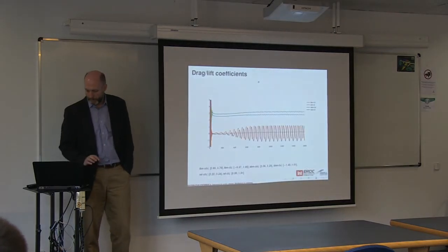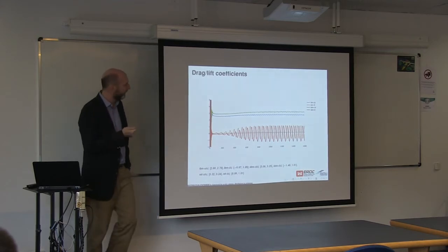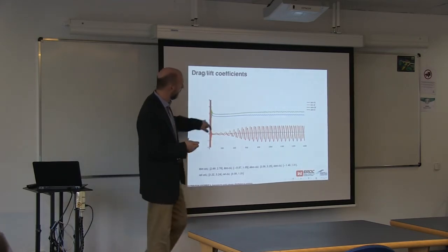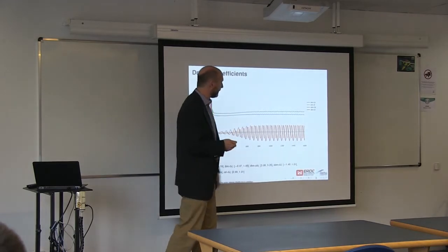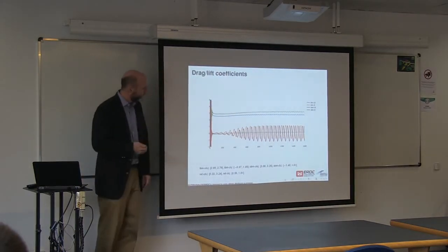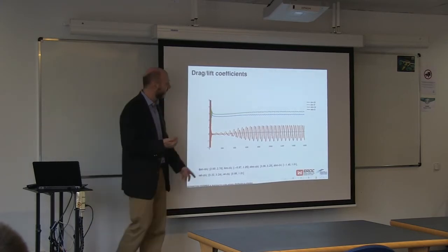If you look at the drag and the lift coefficients, here we're doing a comparison of what we get from the shifted boundary method and from the immersed boundary method. The value for a conforming method, and most of the published results, are right around 3, a little bit above 3, so they're closer to our IBM results. And the phasing is a little bit off on the vortex shedding.